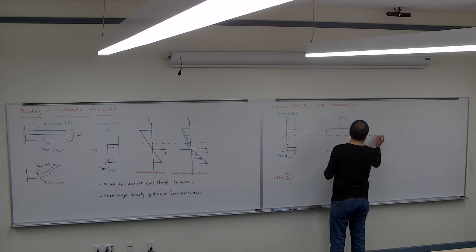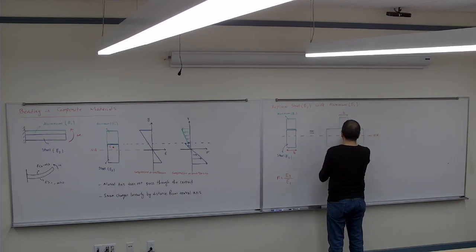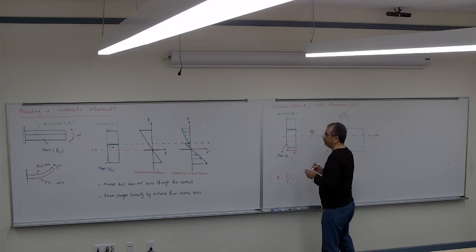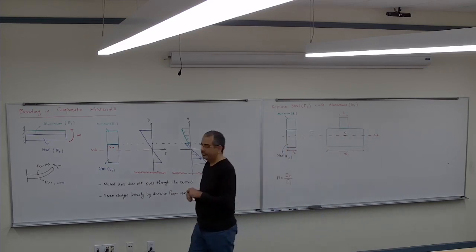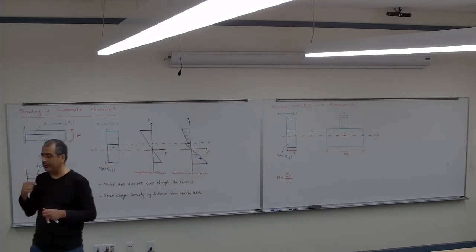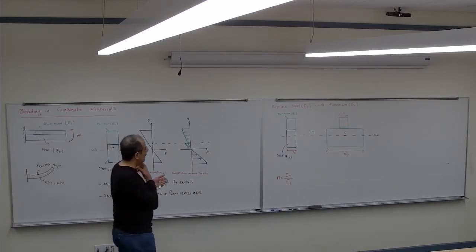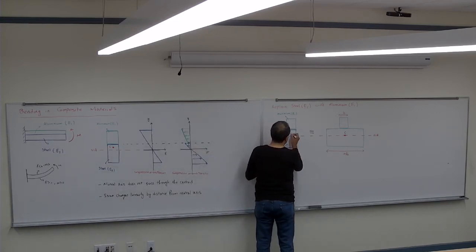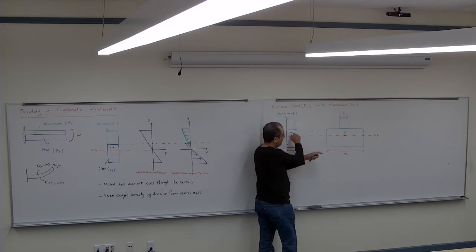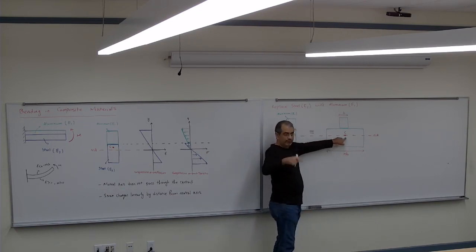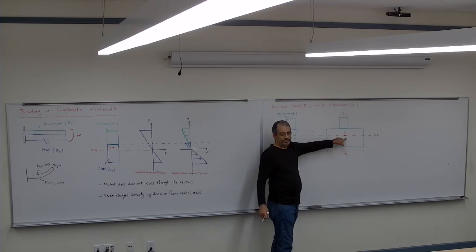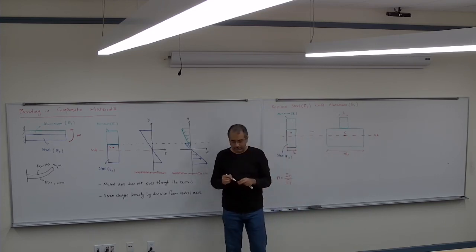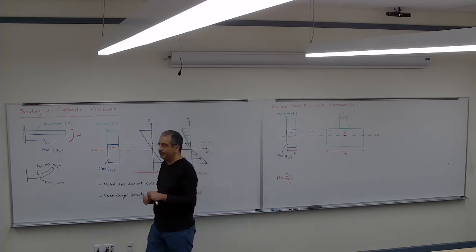This is going to be the neutral axis, the centroid for the new cross section. So it passes through the centroid of the new cross section. It doesn't pass through the centroid of the old cross section. If it's, for example, here, it doesn't pass through that, but it does pass through the centroid of the new cross section. So that's going to be my neutral axis there.